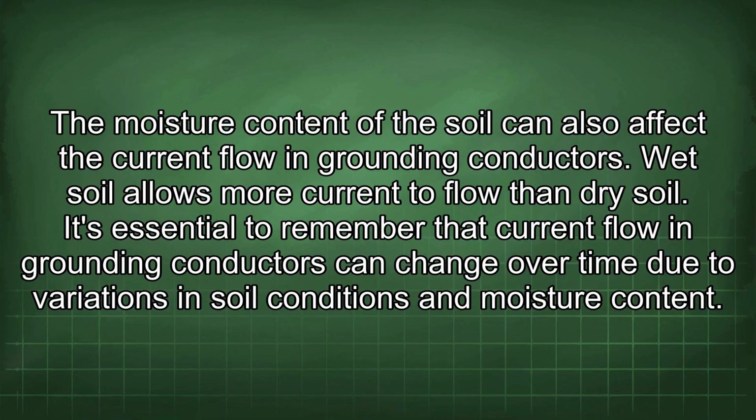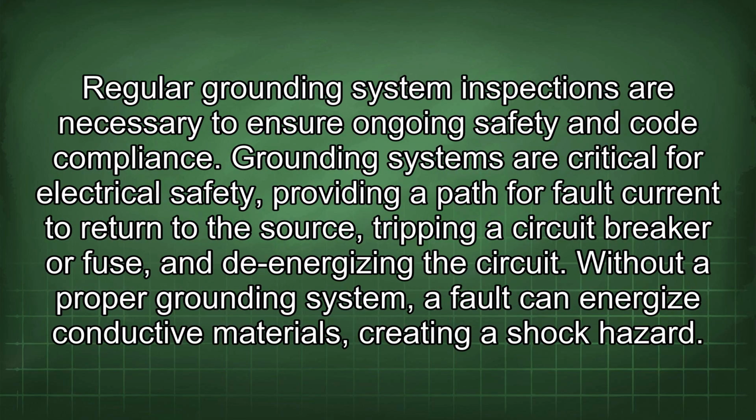It's essential to remember that current flow in grounding conductors can change over time due to variations in soil conditions and moisture content. Regular grounding system inspections are necessary to ensure ongoing safety and code compliance.